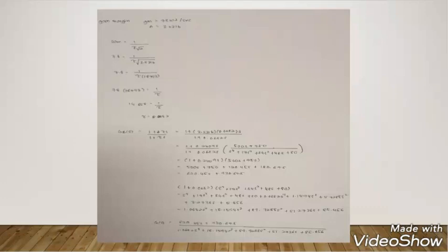Then to get a new Bode plot, you must substitute the values of alpha and tau into the Gc(s) formula, (1 plus alpha tau s) over (1 plus tau s), where s is the s domain.